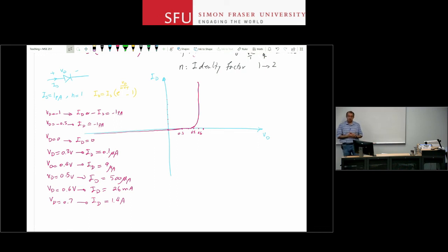So this is the exponential growth that we are familiar with, from high school physics or from the pandemic that we're going through. The exponential growth is right there. Just a tiny, tiny change at the input makes a huge change at the output. Now, this relationship, amazingly, is valid for 7, 8 orders of magnitude variations in current. It's one of those nonlinear relationships that is holding up to a lot of change in ID values, amazingly.